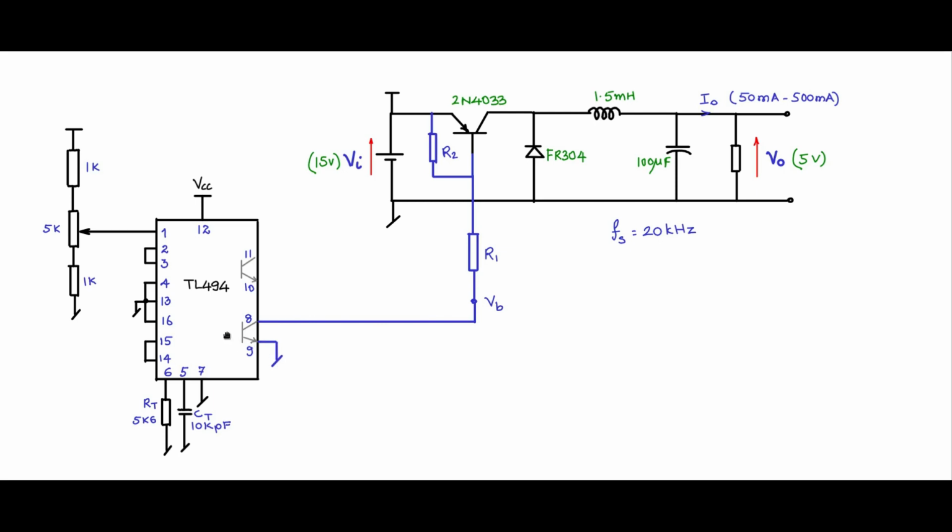Now let us say the internal enabling pulse is removed for the internal transistor. This is open. When this is open, pin 8 is floating. So there is no chance of current to flow through. Current IB on can't flow here. BJT is off. So in this way BJT can be turned on or off by controlling the internal enabling pulse to the internal transistor of the TL494.